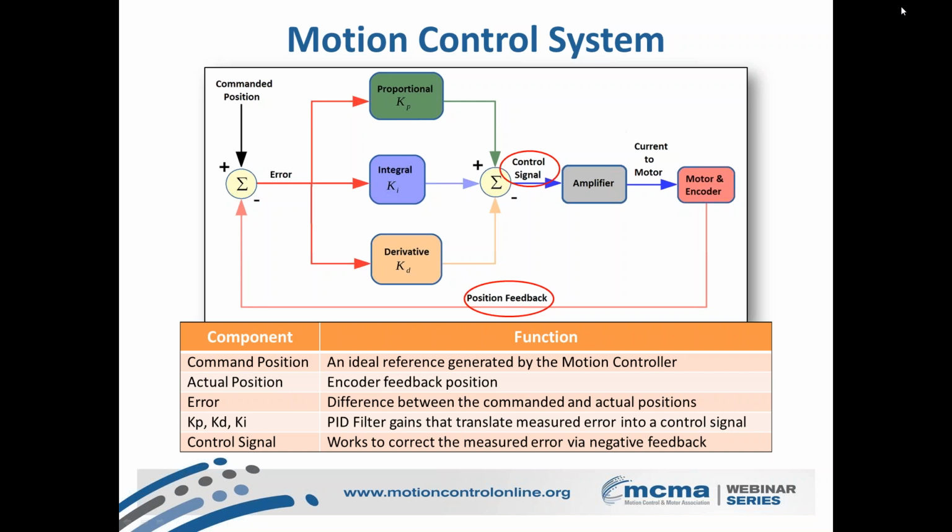This becomes especially problematic if the motor amplifier and motor need to be physically separate from the controller, over large distances, 50, 100 feet or more. The longer that those analog signals travel, the more susceptible to noise they are.